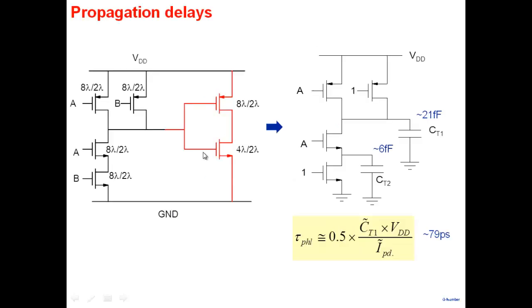So this also tells you that if there's a NAND gate in your critical worst case path that we saw here, where should you put that input? You should try and put the critical input here. Don't put it at the lower one. The lower one will add more delay, right? The 2 inputs are not equivalent. That's an important point to keep in mind.